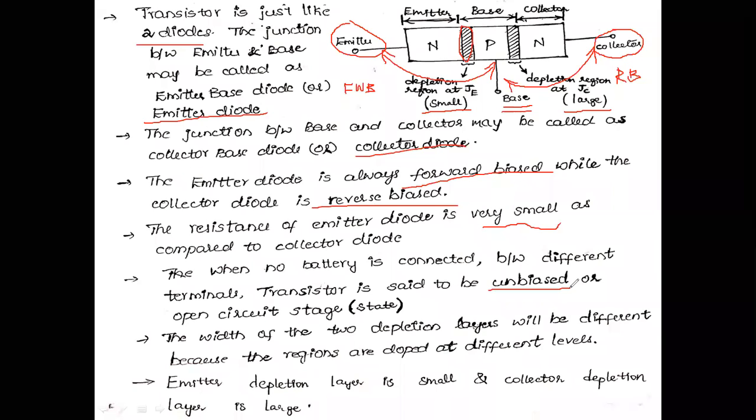By applying some voltage to the PN junction diode, the drift will take place. The drifting of majority charge carriers from one terminal to the other will take place, and a drastic flow of current will occur due to the movement of the electrons. That is the drift concept, which happens by applying the voltage, whereas the diffusion concept is a natural process.